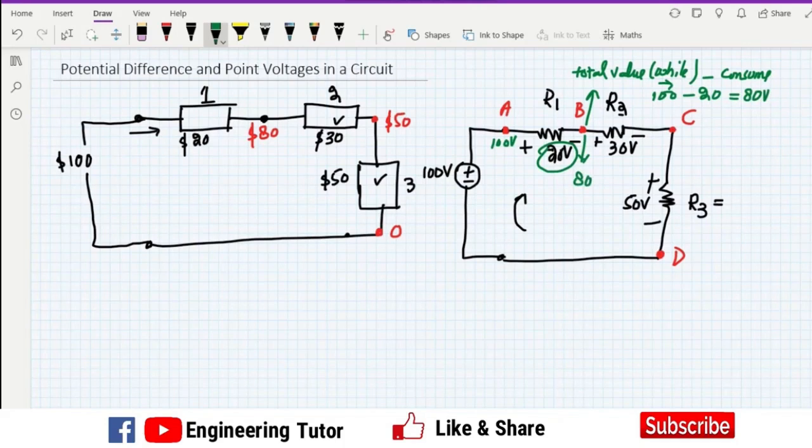Similarly, when this 80 volts has come here, the current has passed through this resistor, and now 30 volts are consumed. What will be the value at point C? That would be 80 minus 30, the value of money which a person had entering a shop minus the value which was consumed, equal to 50. Similarly, here we have 50 volts. When it enters through this one and leaves it, the value here at D will be equal to 50 minus 50 volts which was consumed, and it is 0.